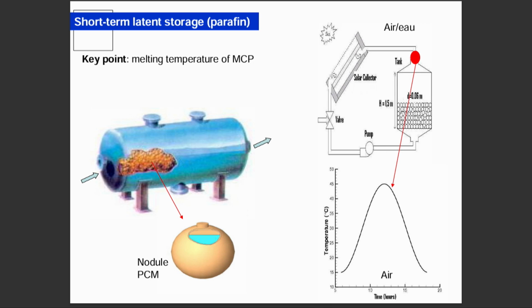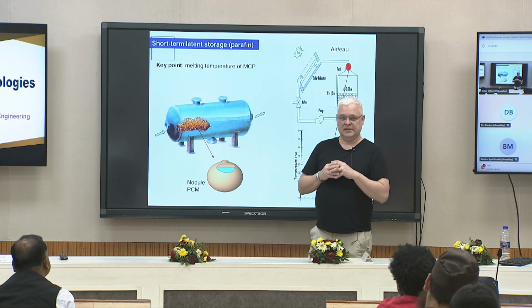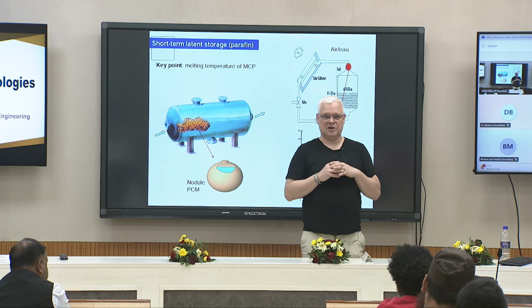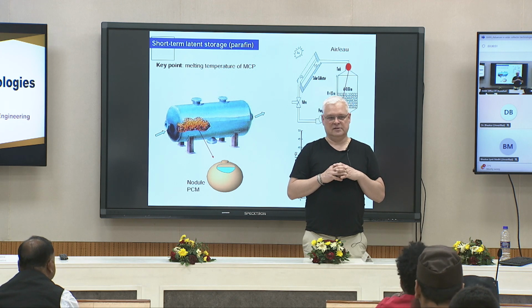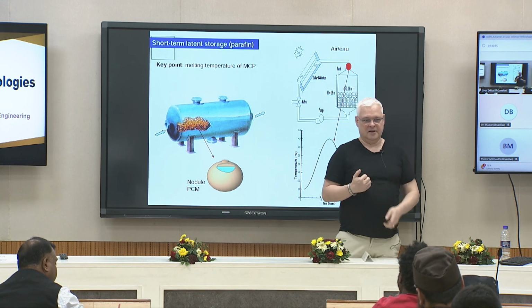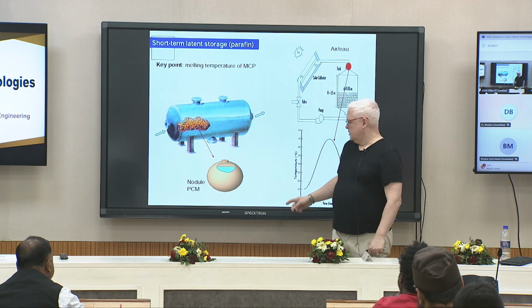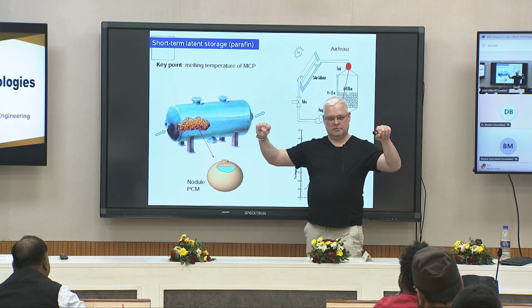One thing to be cautious about when you put phase change material in a finite volume is that the volume changes between liquid and solid. There were a lot of problems in the first experiments where it was fully filled and exploded.